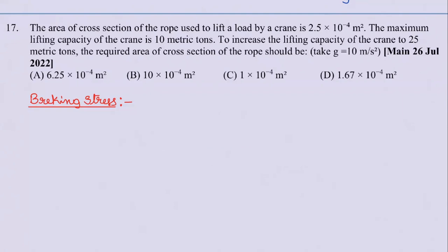Just remember, strings break because of stress. This statement emphasizes that, be careful, the breaking is decided by stress, not by force. If you double the radius, the area will be 4 times, and you need to apply 4 times more force to break it.